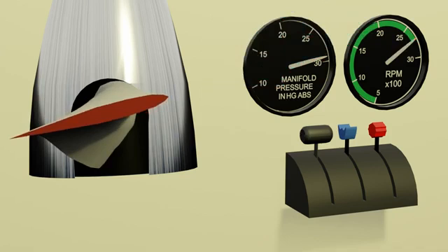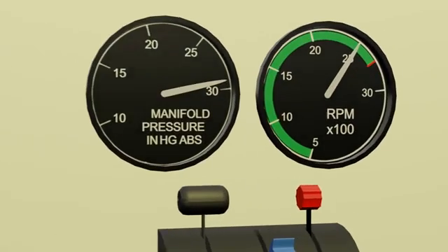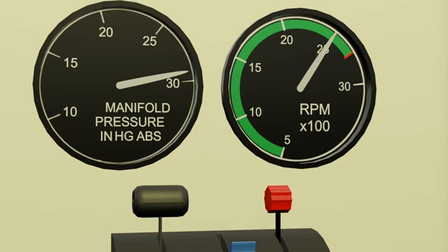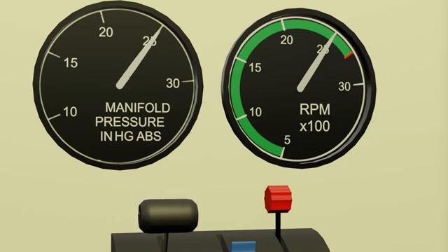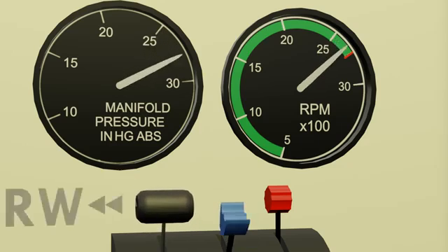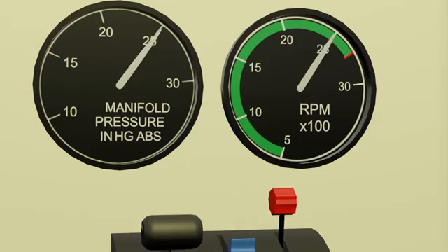Starting from the departure climb, the propeller lever is reduced to the climb power setting. Why? To save fuel, that's all. Sometimes operating procedures call for what's known as 25 squared, or 25 inches of manifold pressure and 2500 RPM. The order here does matter. Throttle, then propeller, then mixture.